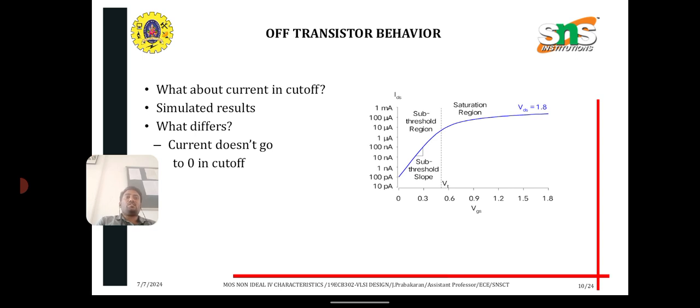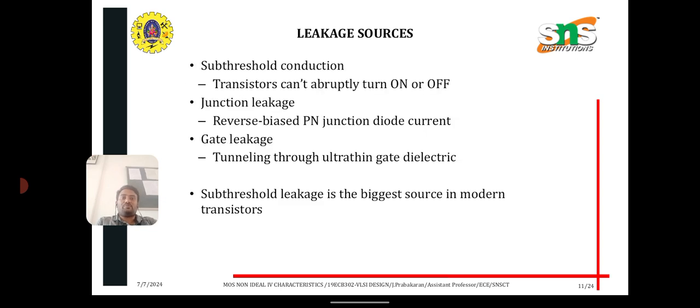Understanding the off-state behavior of transistors is crucial for designing efficient and reliable CMOS circuits. Leakage current can affect power consumption and overall circuit performance. Leakage mechanisms include gate induced drain leakage, drain junction leakage, and subthreshold leakage, which increase off-state leakage current, impact power consumption and reduce battery life in low power applications.